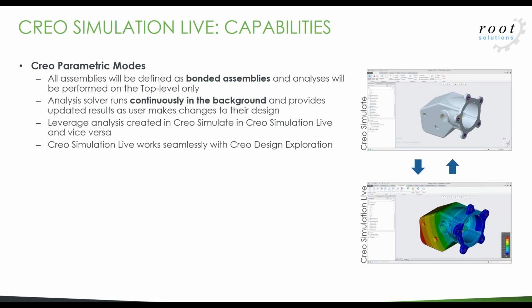Just a bit of an overview with the simulations themselves. We can work with part or assembly level simulations. The assembly side of things will be treated as a bonded assembly, so it assumes everything is connected and will be performed at the top level. These simulations, as James said, run continuously, so this is where it really helps us with that design phase. We can go in and make live changes to our model, be that at the assembly or part level, and see how that alters our analysis, be that structural or whatever it may be.